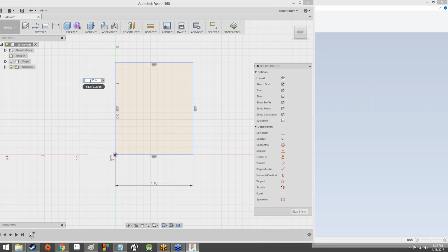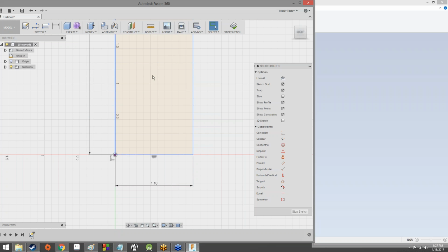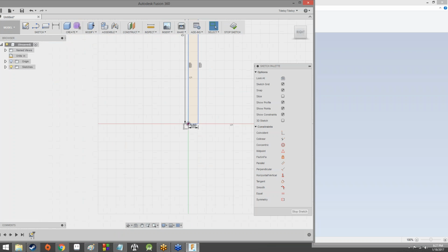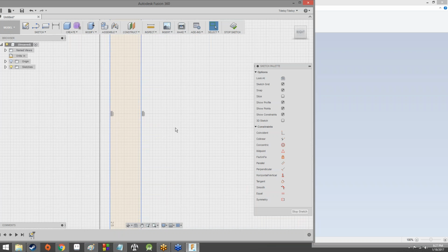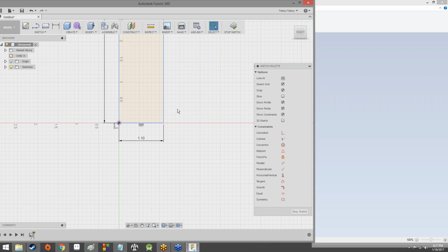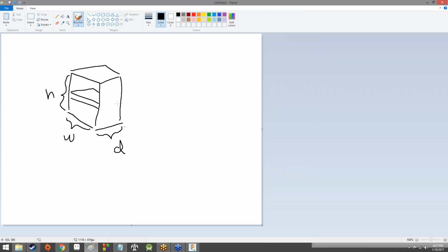So let's actually just go ahead and do that. We'll replace this with height with a capital H. As you can see, it auto-completes with that. I'll click on it, bam, hit enter, and it gets huge. As you can see, I drew that rectangle really tiny. But this bottom one in particular I'm interested in. If we're looking at the bookcase side on, what do you think that bottom one is going to represent?